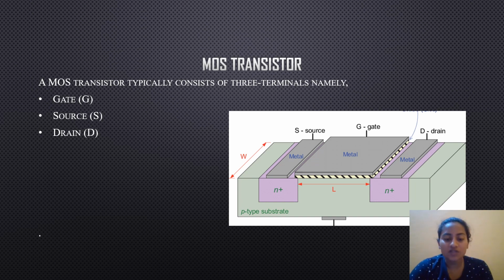This ability to change the conductivity with the amount of applied voltage can be used for amplifying or switching electronic signals. A metal insulated semiconductor field effect transistor is a term almost synonymous with MOSFET. Another synonym is IGFET, for insulated gate field effect transistor.